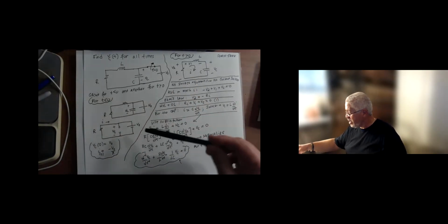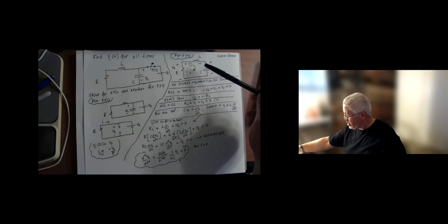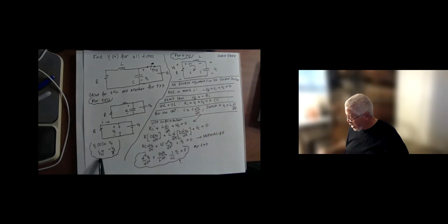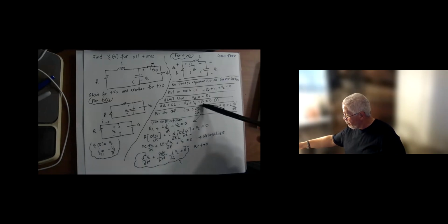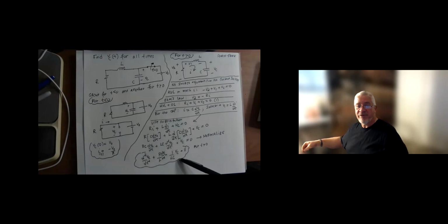When the switch opens up, we get a source-free circuit here. So we had to calculate the initial conditions, which are the inductor current and the capacitor voltage. So we learned how to do a full mesh analysis, even though it was a one mesh circuit, but it's a pretty comprehensive process to get our differential equation here.